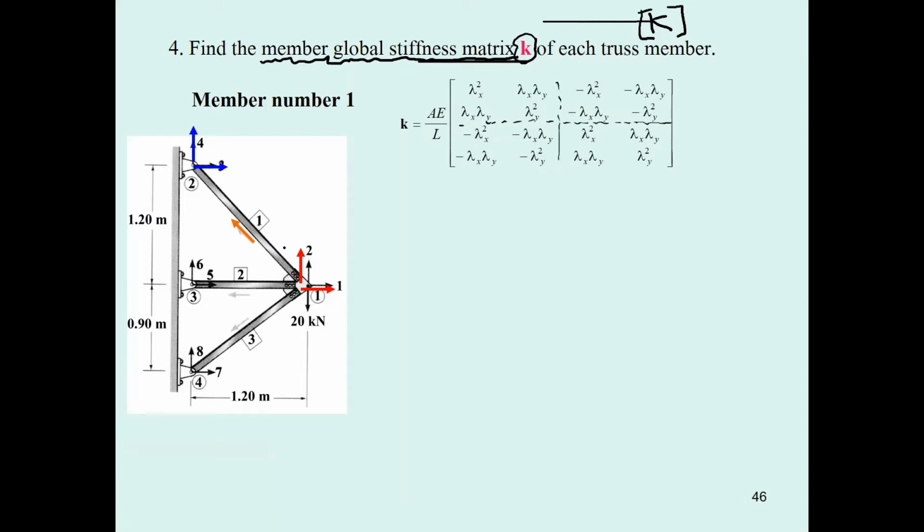And you can see for a given member, for example member number 1, you will have the near end here and the far end here. In front of this matrix is the stiffness, and the force, and at the other end of it is the displacement that occurs in this member. It's going to be Q1, Q2, Q3, and Q4 in XY. And over here is going to be capital D1, capital D2, capital D3, and capital D4.